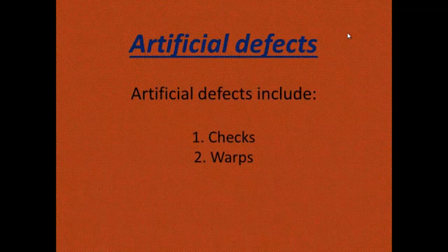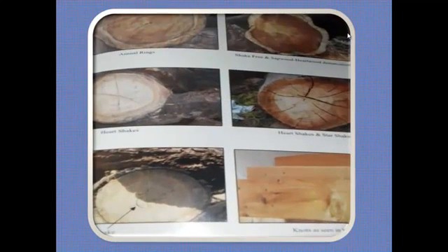Then if we talk about the cross grain, fibers in the wood in a normal tree are usually parallel to the axis of the length of the timber. This structure is called straight grained. In some cases, however, these fibers are not straight and they make an angle or slope with the axis of the tree. They are called cross grains. They are quite defective, as the compressive and tensile strength of wood is closely related to the direction of fibers. The slope should exist within specified limits.